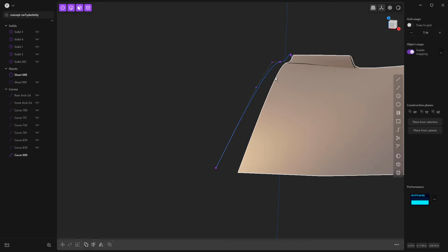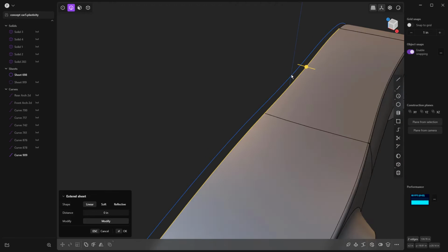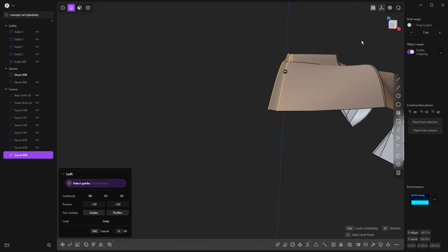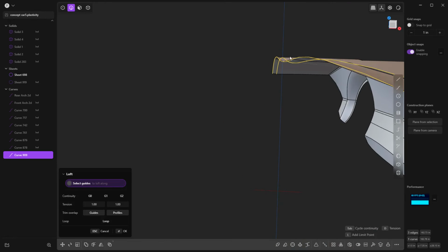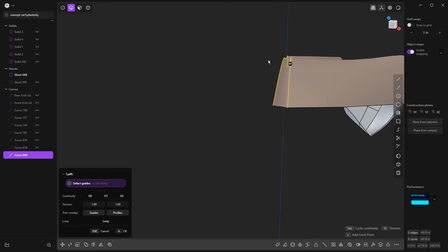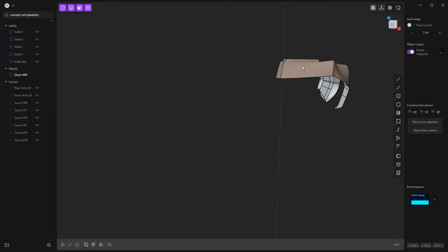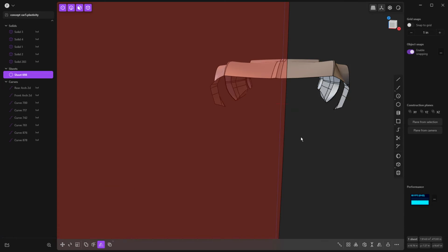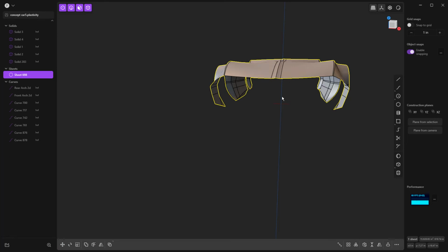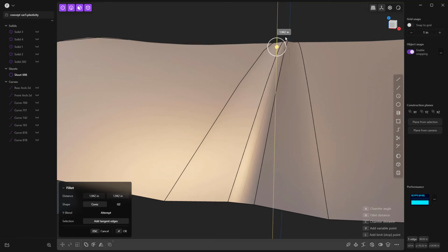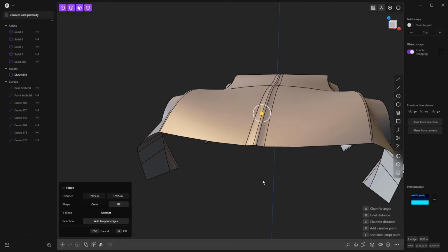And let's try to loft this. All right, so a loft between those. Because now we've got a bit more of a gap, tangency shouldn't be an issue. So I'm going to accept that. We'll join these together. Get rid of that. Get rid of that. And let's try this again. Let's mirror the whole thing over. Join them together. And then now we can fillet that. Do something probably about 2 inches, G2 continuity.